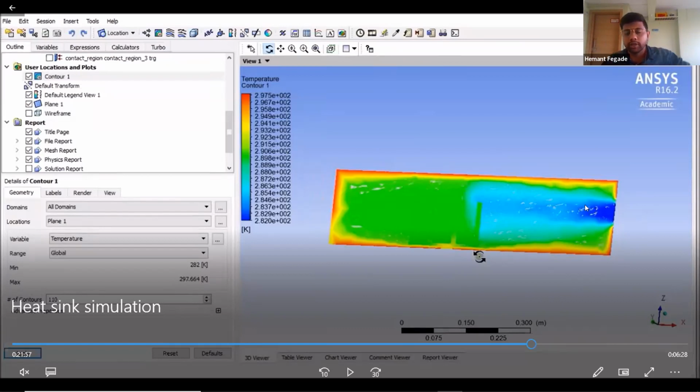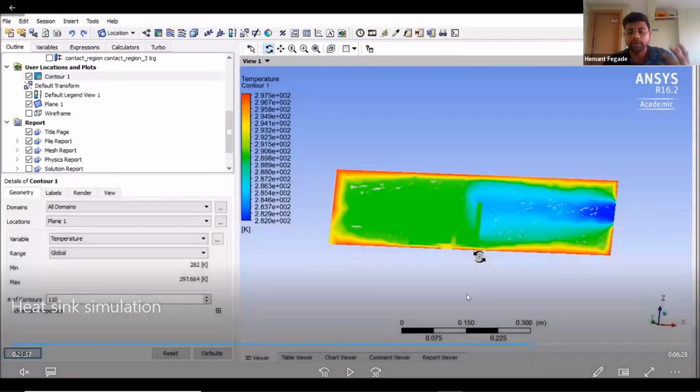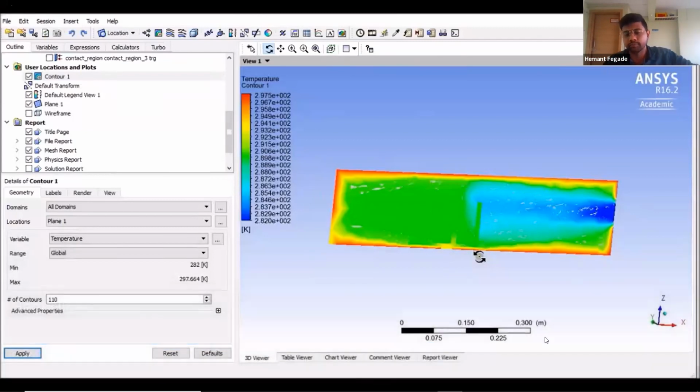where you can see that due to the effect of the air blowing over this domain, the environment is a bit colder. So your temperature is in the range of 287 Kelvin, 286 Kelvin. In that range, your temperature is in this sky blue color region, whereas in the greenish part you will have slightly higher temperatures, 290s, 291. So that sort of regional difference is there. This is how you can establish the results, and how you can analyze the results.